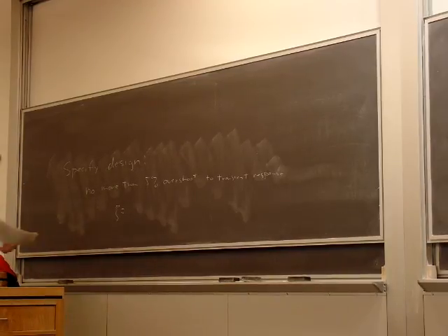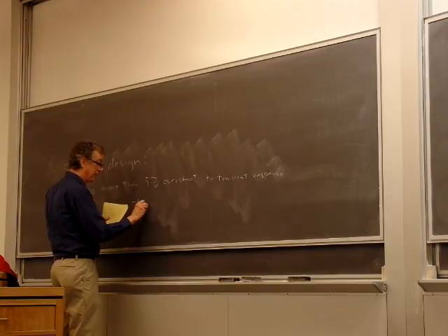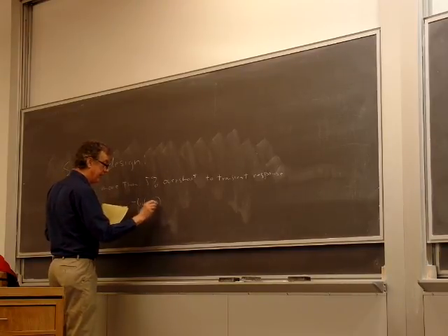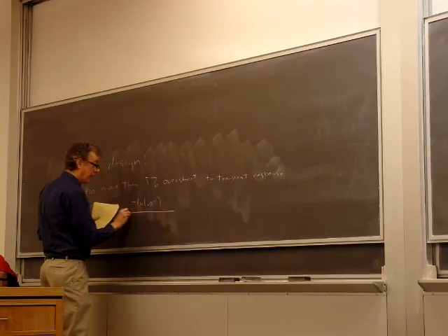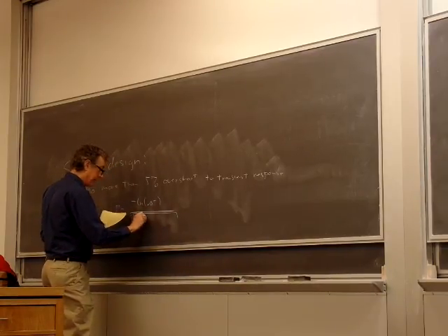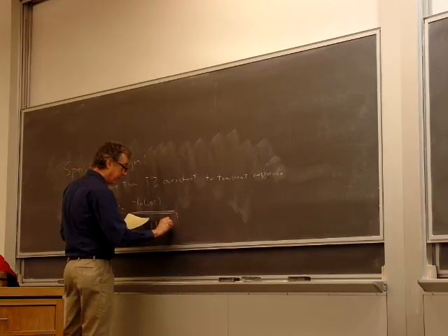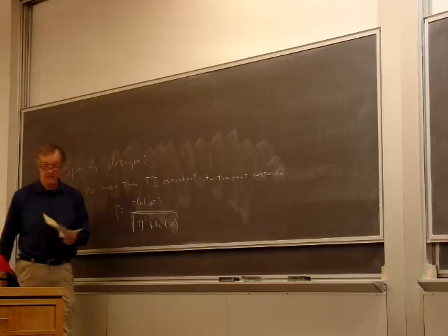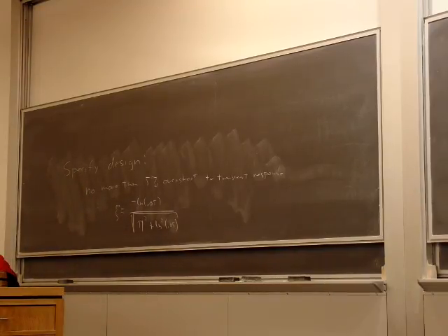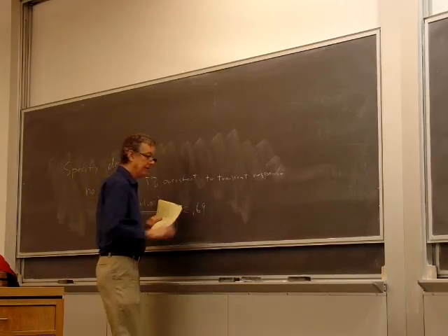Zeta is minus the natural log of our overshoot, which is 0.05, all over the square root of pi squared plus the natural log squared of 0.05, and that's equal to 0.69.